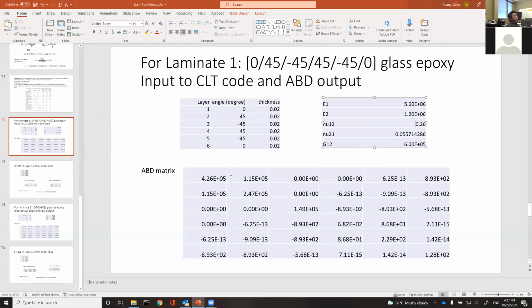Now, the exact same code, you can just stick in different units. Let's say you decided to use Pascal for your modulus, and then a meter for your length measures, and then Newton for your force, and then you don't need to change anything. It should just work. So that's the best way. You should have your code dimensionally neutral. You don't want to freeze it so that all the input has to be in certain units. It's too rigid.